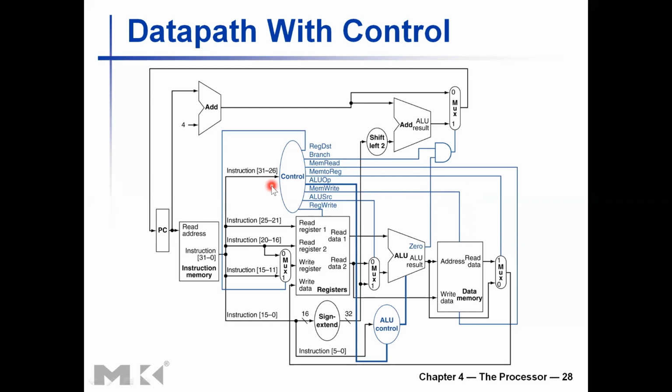Okay, so after that, the mem to reg signal, this fourth signal here. It is sent to the multiplexer, which is at the output of the data memory. The control unit looks at the opcode, generates this mem to reg signal, and sends it to this mux.